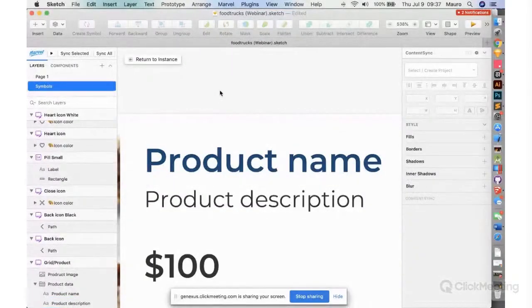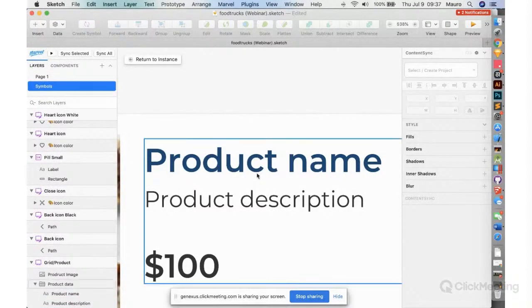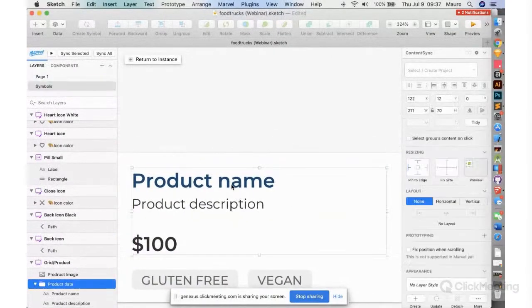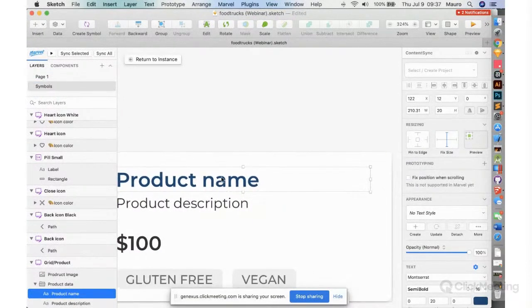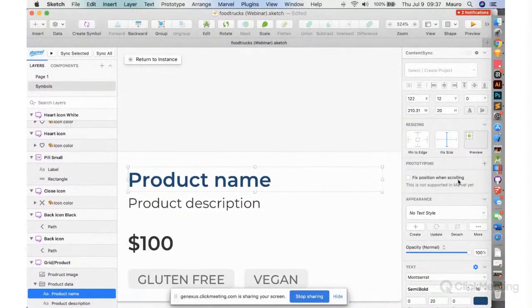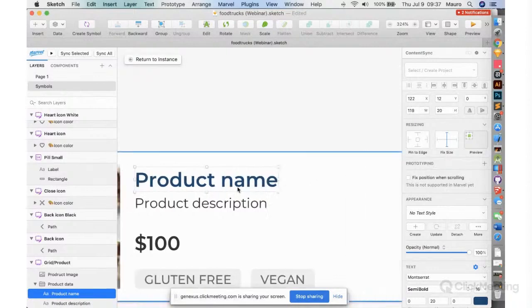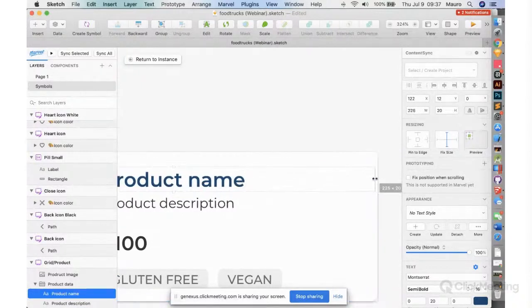So avoid overlapping elements if not necessary. Pay attention to the text frames. Also, for text frames, it is really important that you use the frame to give space to grow horizontally and define those margins right here. So avoid doing this. Try to make the frame as big as possible and define the right margin or the left margin.